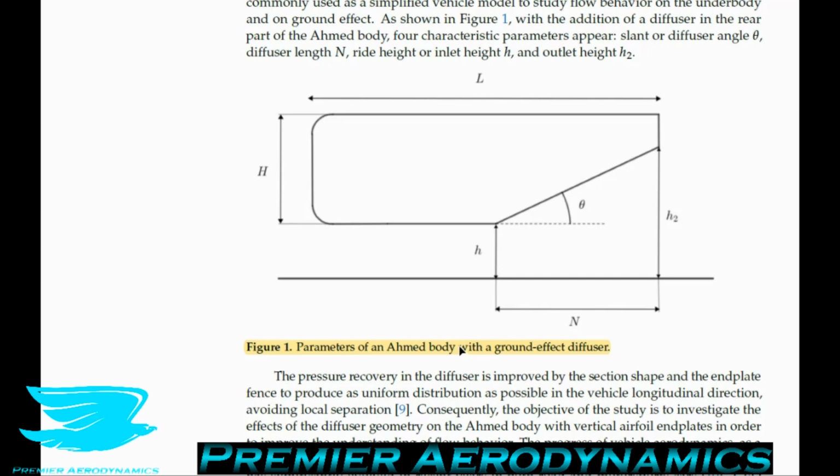So in this particular case, the Ahmed body is a standard bluff body geometry first proposed by Ahmed and others in 1984 to study how adding a slant angle at the back, so the backlight angle of a car, influences the flow field and resulting aerodynamic forces. They show this in figure 1. Initially, imagine a rectangular prism, and the front is rounded a little bit. Then the back top corner has just been chamfered off, so it's now a slant. That's what the Ahmed body is. However, in this particular case, they're flipping this over so that that slant is now on the underside.